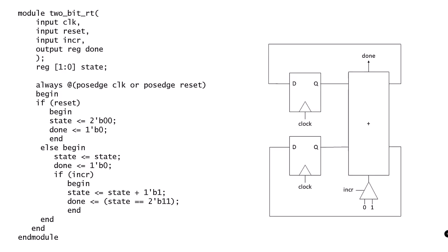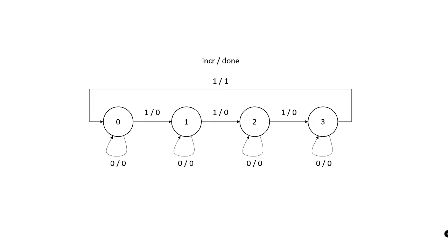A counter is another useful sequential machine. This counter is specified as a register transfer machine with an adder and registers for the bits of the value. The carry input to the adder controls when it increments. When increment is 0, a 0 is fed into the counter, resulting in no increment. When increment is 1, a 1 is fed to the counter, resulting in an increment. The carry out of the adder provides the done signal.